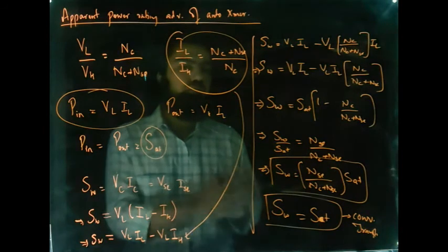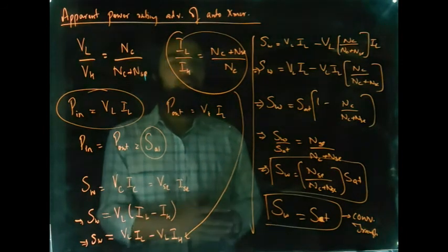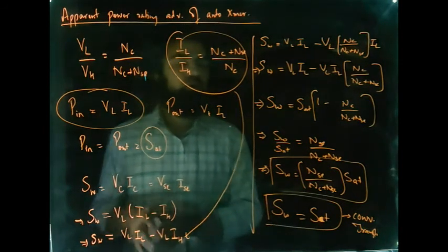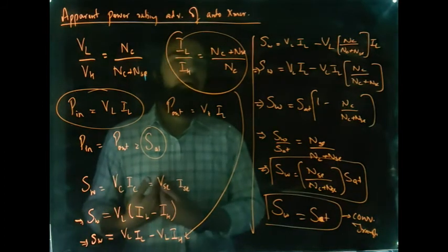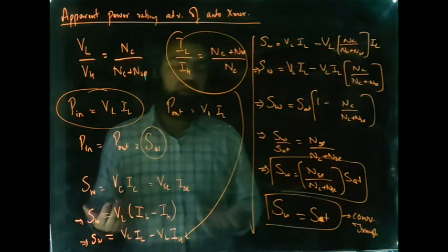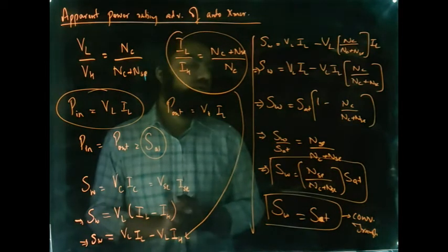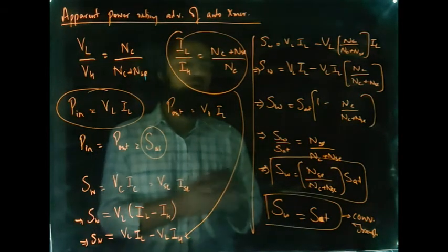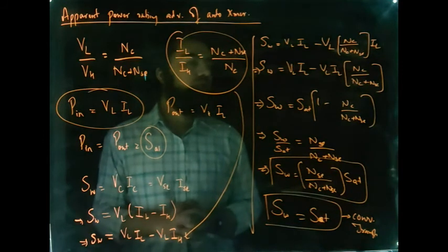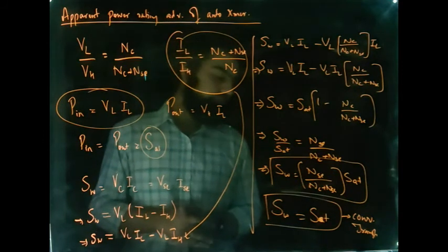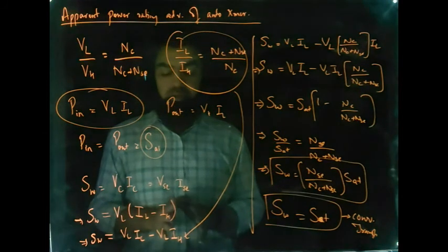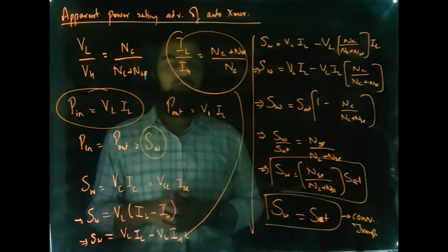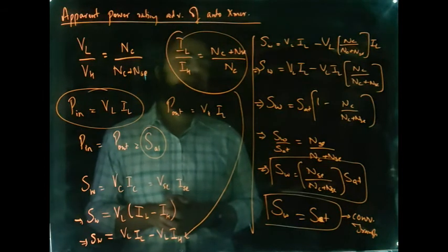The power rating of the winding is much less, so we can design the same auto transformer cheaper, and the size will be less. So it is going to be cheaper on two accounts, because it is going to consume less winding, as well as the power requirements will be less for the winding. So this is an advantage with an auto transformer over a conventional transformer.